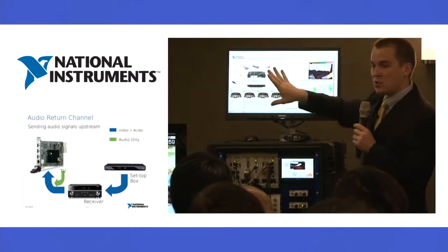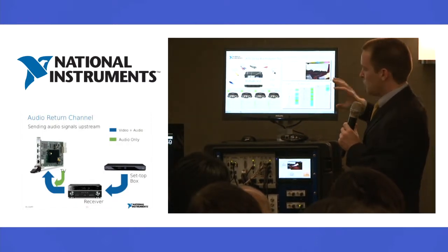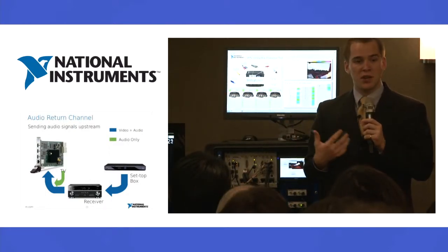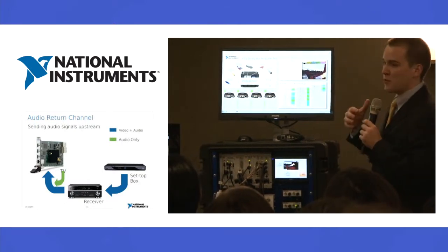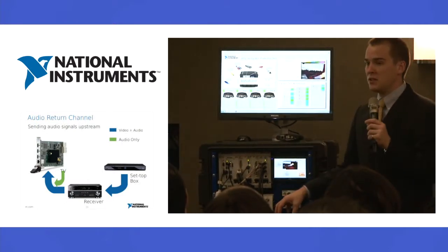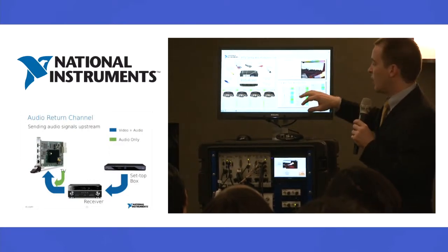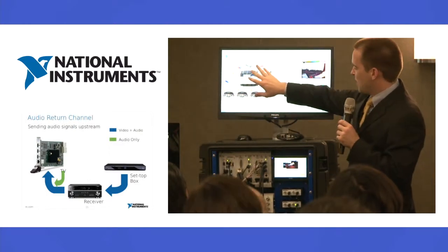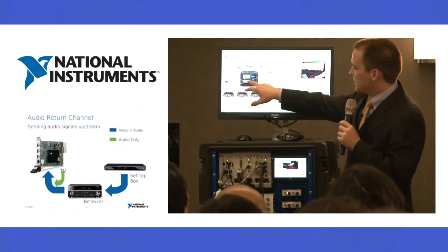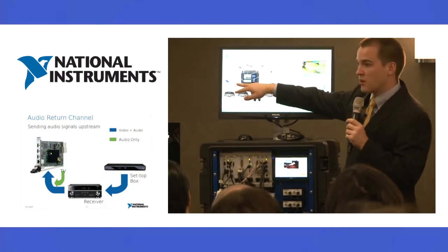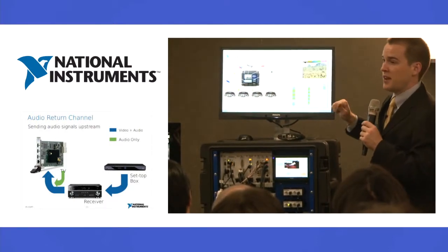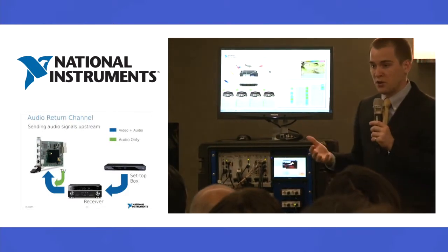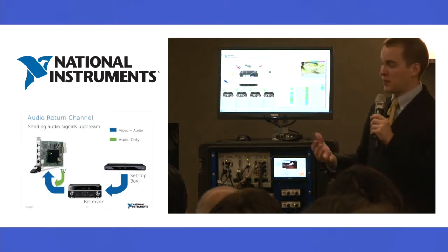So this is a custom user interface I made. You can do this using LabVIEW, but basically when you've got an inspector, or a technician, or an operator on the production line, you don't want to give them all of the information that comes from each of these devices. You want to simplify it down to just what they need to know. Which components failed, and how did the DUT do overall? And maybe up here we have the different instrumentation, which DUT is it plugged into right now, and how long did it take to test, things like that. So you simplify down what you have on your user interface. You make it very easy for an operator to be able to use this. And you as the engineers can develop this rapidly.